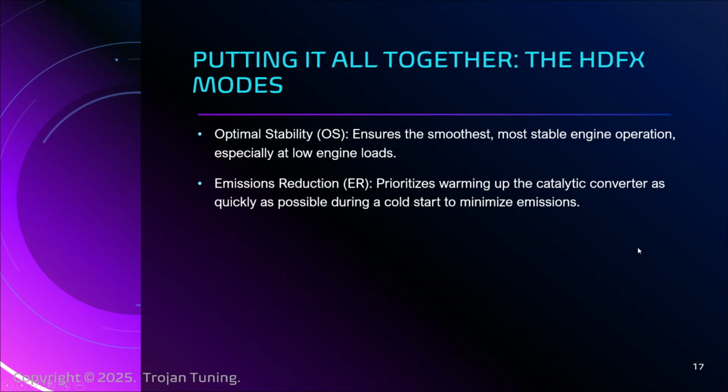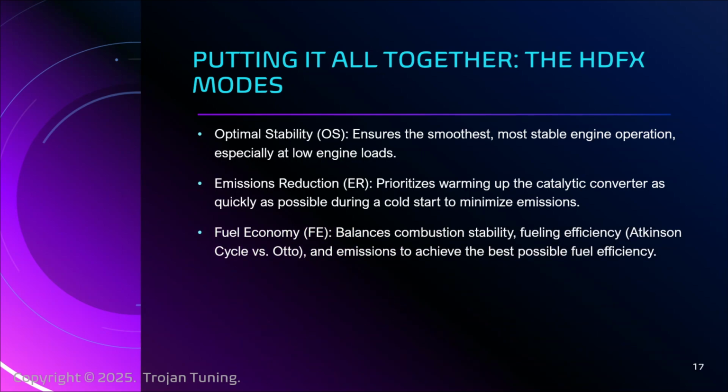Emissions reduction, we really don't have to worry about this one. This is where, when you first do a cold start, emissions reduction will warm up the catalytic converter as quickly as possible to get it working, and it really puts power into that and prevents things from getting too crazy in terms of fueling and air until that cat is warmed up. It really only lasts about 30 seconds. When we are logging, we wait until we're at operating temperature before we do our logging, so we don't have to worry about this, and I won't say any more about it. Fuel economy. Okay, so combustion stability.